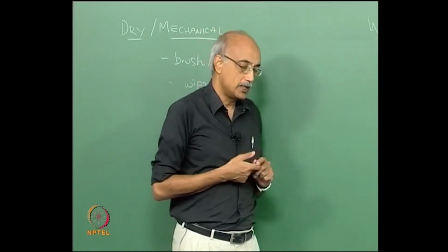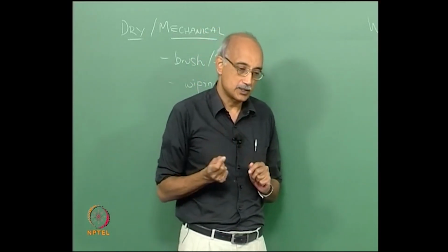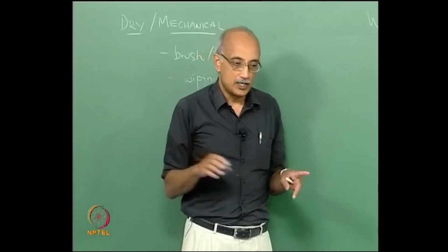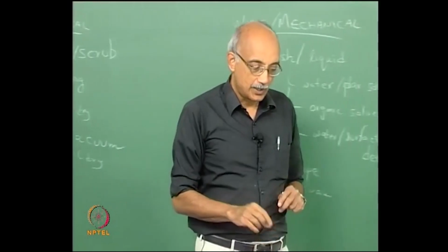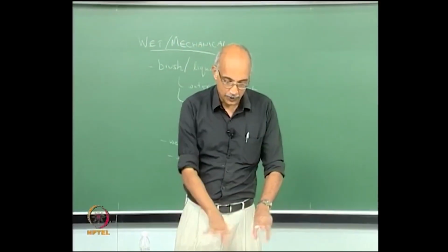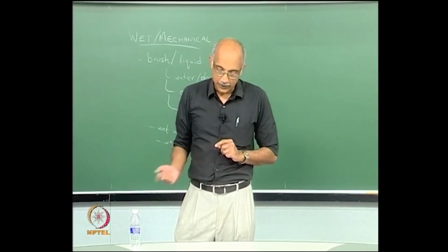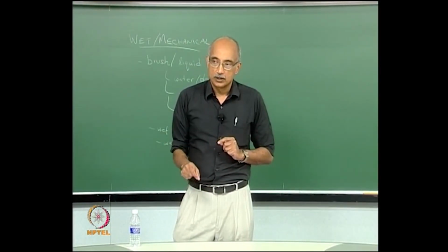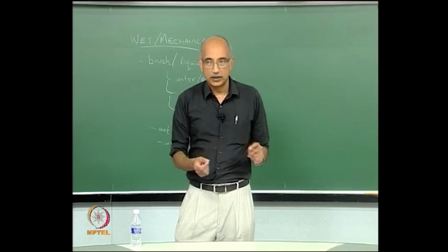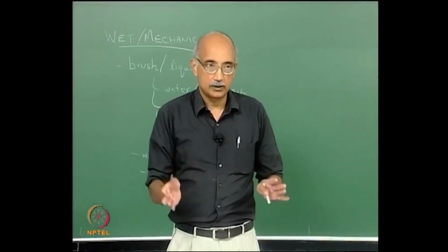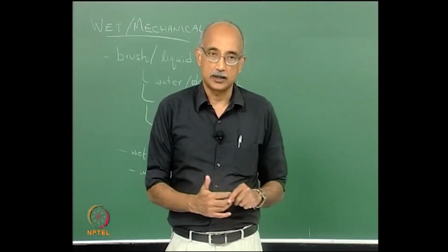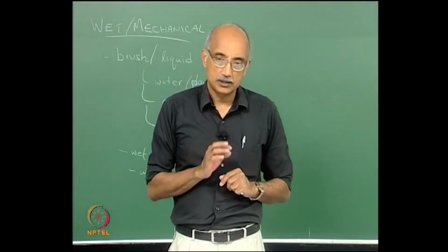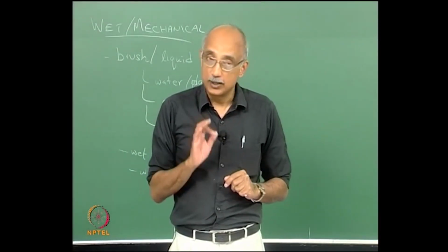So vacuuming has huge advantages because it's an in situ process. In other words, if I'm running a manufacturing process here and I see some contaminants and this is my workstation, then I can just take a vacuum wand and just pull off the material right here. If I have to do a wet cleaning, I have to take it out of the clean room, clean it, dry it, and then bring it back in. So vacuuming has a lot of advantages in terms of convenience, can be localized.